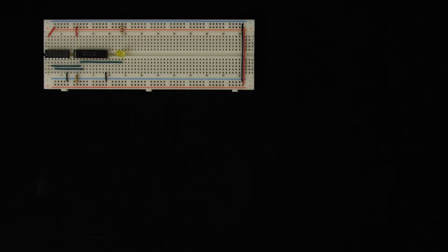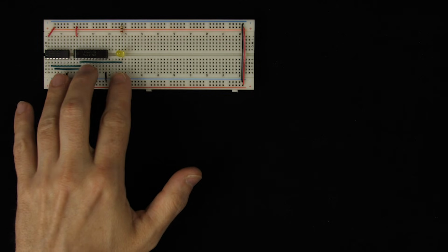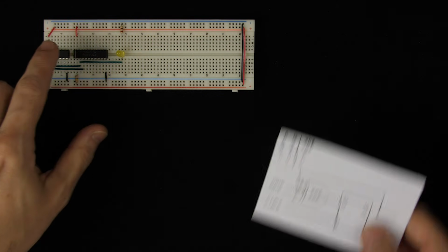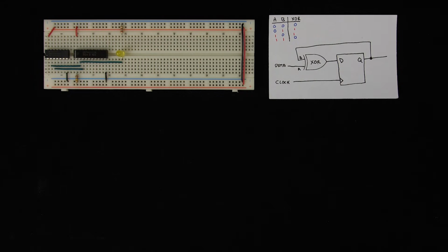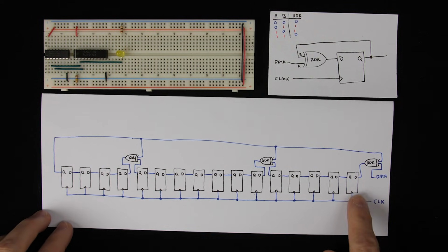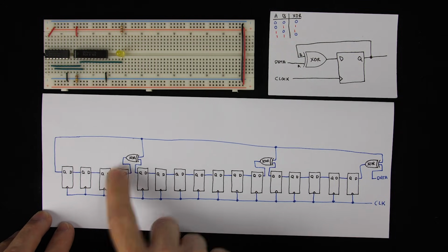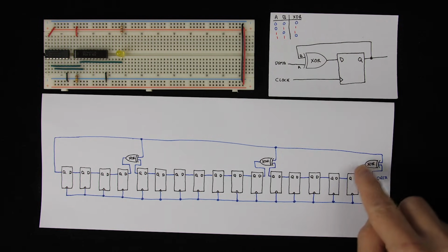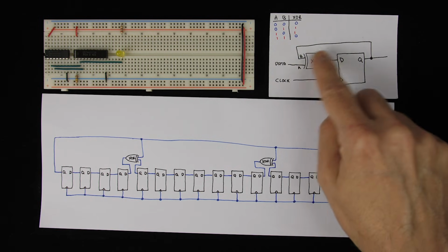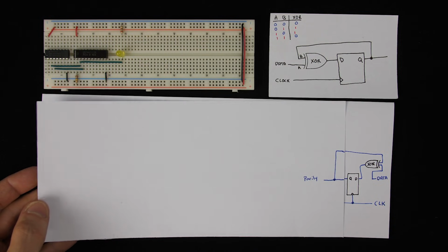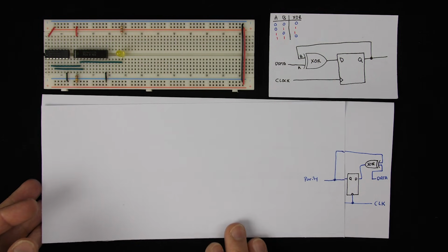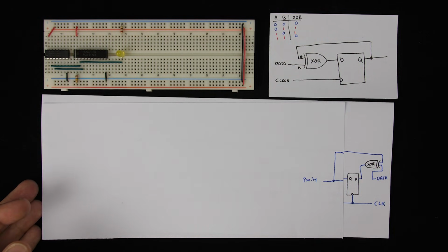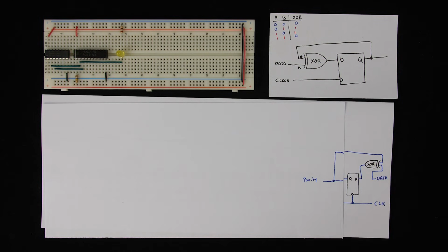But one last thing that I'll point out that I think is kind of neat is that you may have noticed that there's some similarity between the circuit that we built for CRC and the circuit that we built for computing parity. Both use an XOR gate and D flip-flop. It's just that in the case of CRC, we've got a bunch of D flip-flops and a number of XOR gates. And in the case of parity, we just have one of each. But if you look at just this first bit over here, the circuit's actually very similar. It's drawn a little bit differently there, but if we just cut out the rest of these D flip-flops, this first part of our CRC circuit we can modify very simply to compute parity.